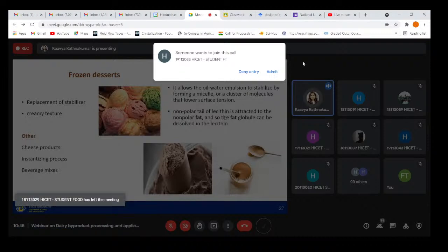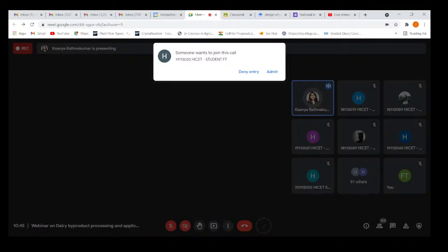So, as in powders which can mix instantly with water to get a whey protein beverage or a shake. In the instantization process, we have a lot of instant powders. Once the powder is obtained, it goes through a process called agglomeration. Agglomeration is a process where the powder obtained from spray drying is further re-wetted using a lecithin.